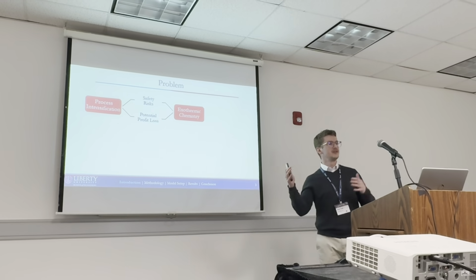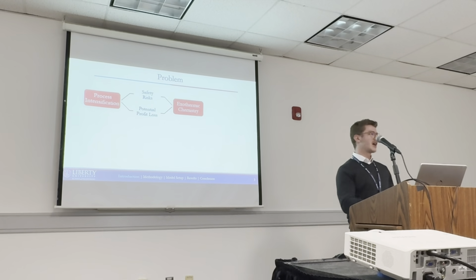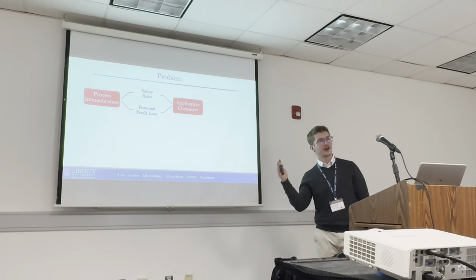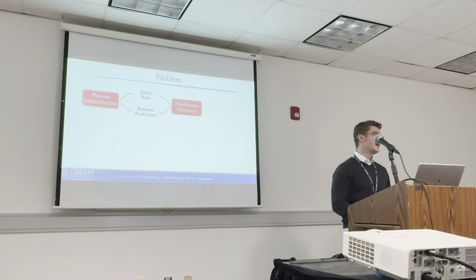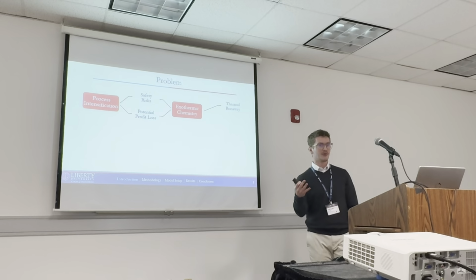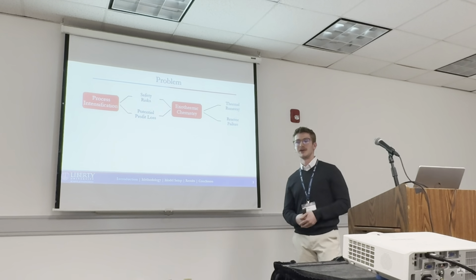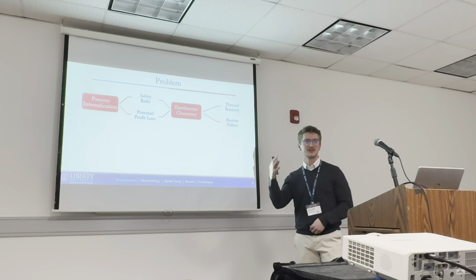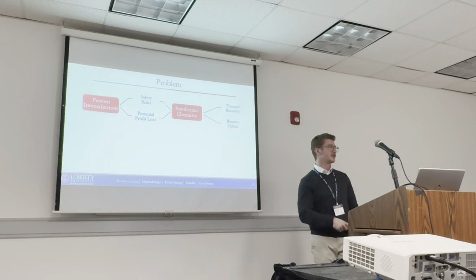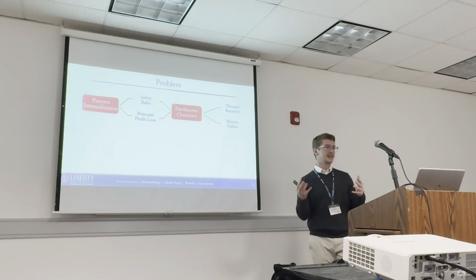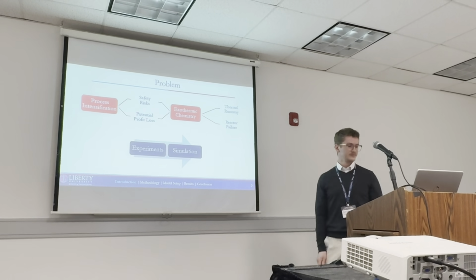We all know that these reaction rates are non-linearly dependent on temperature. So with exothermic chemistry, reaction rates occur, heat is added, the temperature increases, which increases the reaction rates, and creates this kind of snowball effect called thermal runaway. And if that's not mitigated, we can have reactor failure, which, if not shut down before it reaches some climax, the reactor could explode, and otherwise you have to shut down the reactor, kind of flush all the contents. And that could take an entire day and a loss of hundreds of thousands of dollars for the producer.